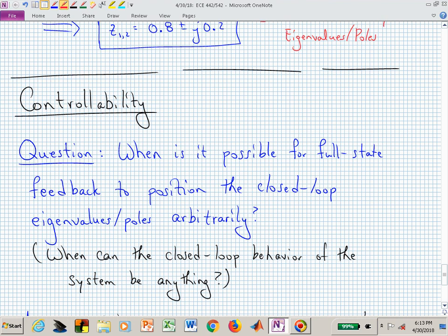And if it's oscillating, you probably don't want it oscillating with no frequency. Where would that be? At 1. So if you put all your poles at z equal to 1, then you're just stuck. You just put out exactly what was put in.